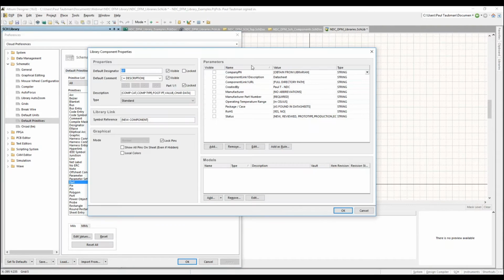So when I click on the part, I went in here and I set all this up. And I made sure that the fonts were the same and that the names, these are the names I always wanted to fill in. Now, more importantly, you'll notice that I have everything in these brackets and in capital letters. Now, that's not to prompt any type of scripting in Altium, but rather when I see these things in a list, that means I forgot to make a change to them. And I need to go in there and make a change to these values here.